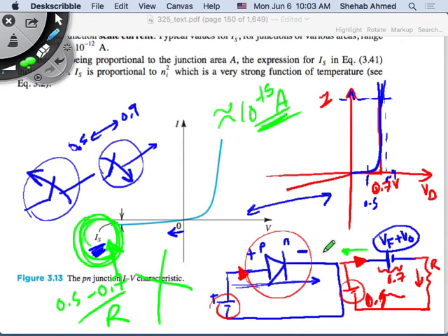You put this device in reverse bias. In reverse bias, you were helping the electric field. You were creating a larger barrier voltage, preventing diffusion. But when you created a larger barrier voltage, you also allowed drift to happen. But this drift is small. So now your external circuit caused you to limit the current in the reverse direction to drift current. So it's like opening the switch.